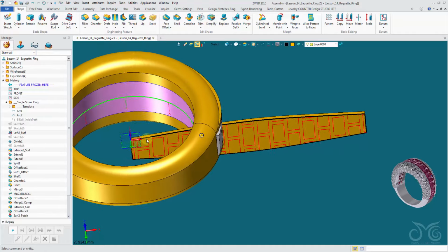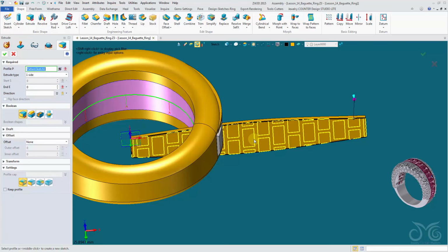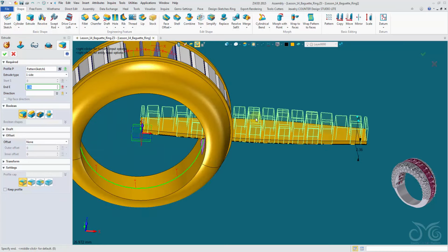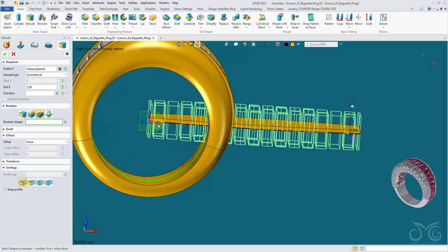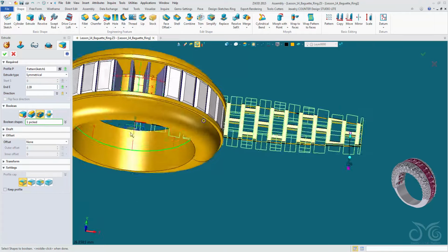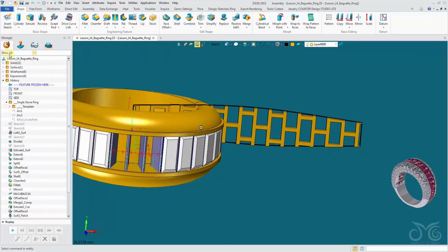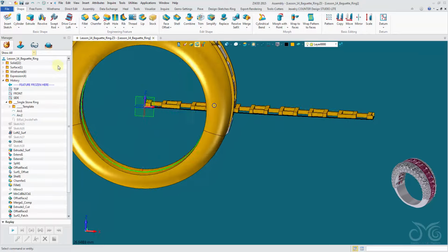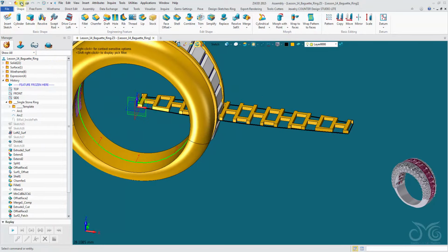Okay, now we will extrude, remove the sketch to create the pierce work. So that sketch is our pierce work, but we want this symmetrical. Remove from this shape only. Confirm the operation. Okay, there's our pierce work.